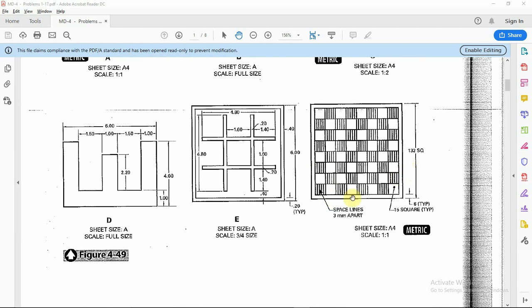I've mentioned before, we want to keep things as concise as possible. We don't want a drawing overfilled with dimensions. We don't want to duplicate. We don't want to give more than necessary. So we'll condense them. We'll make them concise, and we'll use certain things like 2x, 4x. In this case, it would be 32x or 64x. That's a little much, but here they use the abbreviation typical.